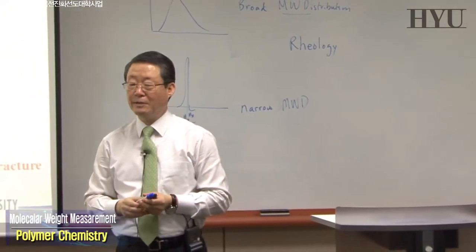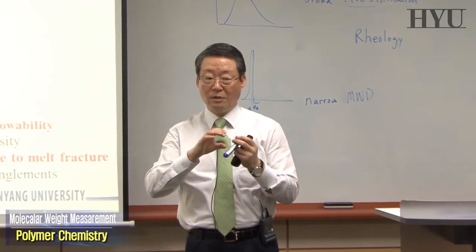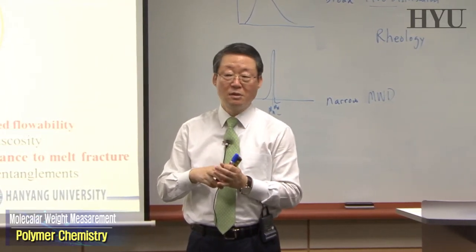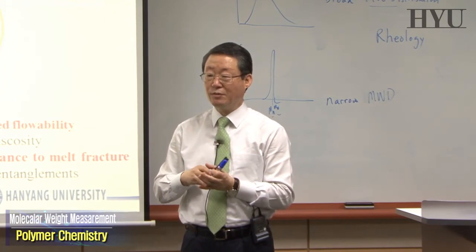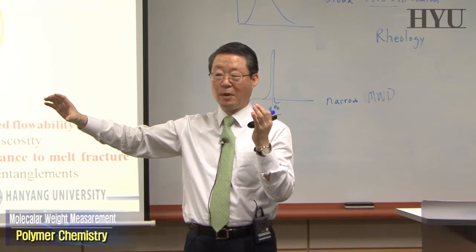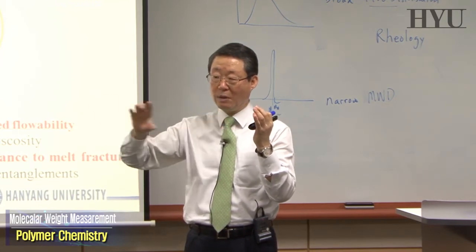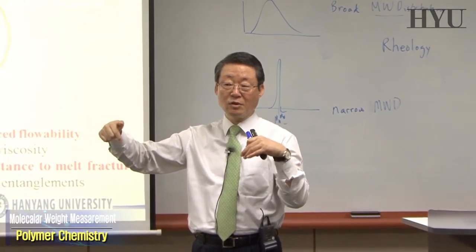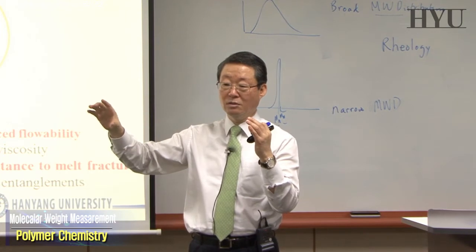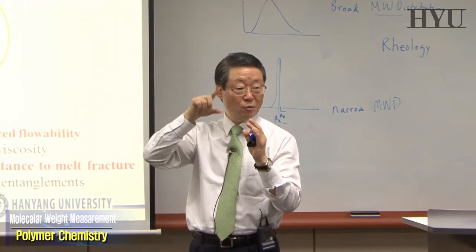Rheology is the study of the flow of your materials. Okay. If you learned about reaction engineering, or unit processes, or mass transfer, or heat transfer, or those transport phenomena, you always have some type of pipes, right? And inside those pipes, you have a fluid, and the fluid should go through those pipelines. If the material has a low viscosity, then you have a low resistance to flow at the wall, right? So in the center line, you have a velocity gradient, of course. So the center is much faster than the wall because of the wall resistance, right?